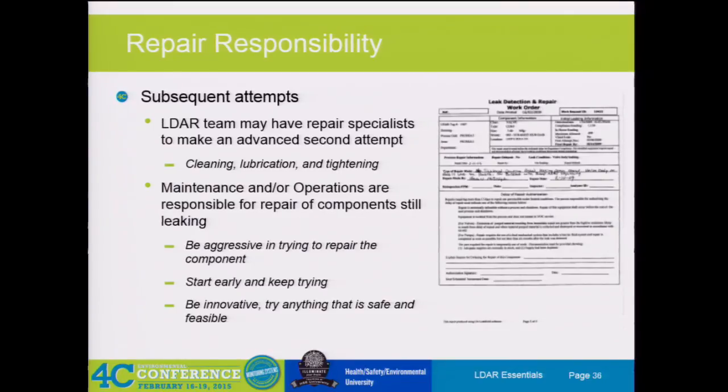What are we at here? Repair responsibility. We talked about who does your repair work. This guy here doesn't let his LDAR technicians touch anything. A lot of plants don't. I do some Colorado Reg 7 work, and we don't touch anything either. There's too much liability in it for us. So whoever does it, a repair specialist, maintenance probably in your situation, you just got to get them out there doing it, and be aggressive about it.